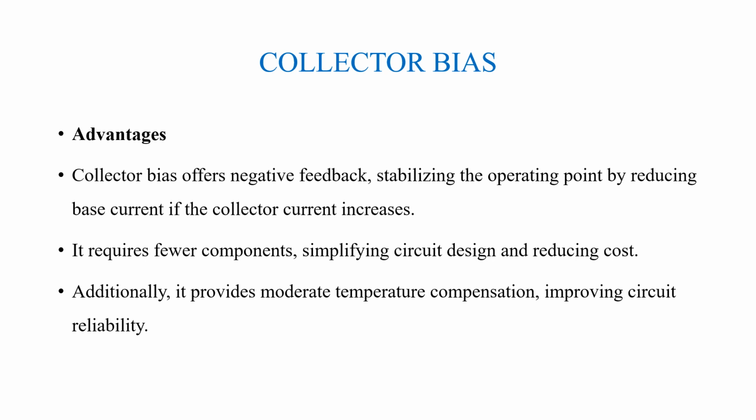Let us check what the advantages are. Collector bias offers negative feedback. It stabilizes the operating point by reducing the base current if IC, that is the collector current, increases.